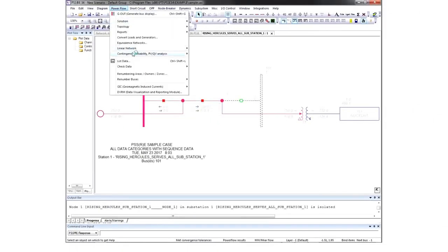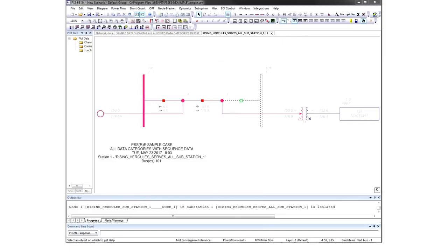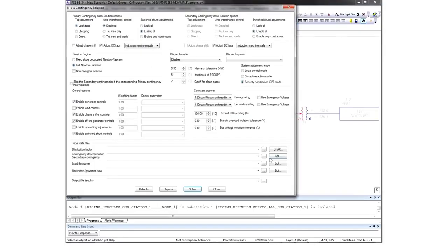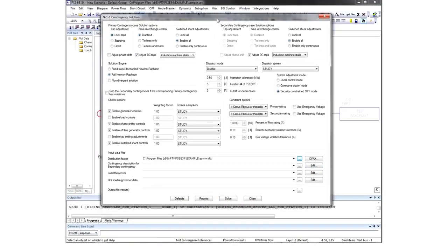Another area of analysis with PSSE is contingency analysis, such as n-1-1. This is a contingency testing scenario where there are two outages that happen, but there is a chance between the contingencies for the system operator to make adjustments to the system.